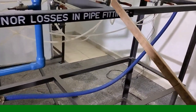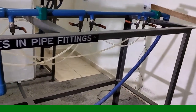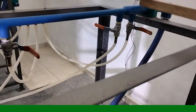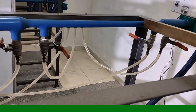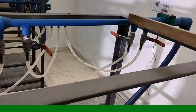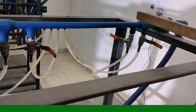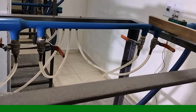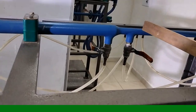Here the diameter is changed from a higher diameter to a lesser diameter. This is called the sudden contraction. This setup itself is one experimental setup, the sudden contraction. To find the pressure at these two positions, different pressure tappings are there. Later, the second experiment is the sudden expansion. Sudden expansion means the diameter increases from a smaller diameter to a larger diameter. Next, the bend is there as well as the elbows.